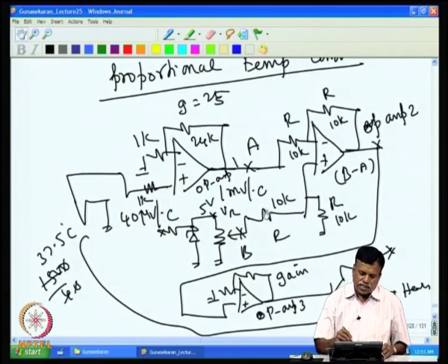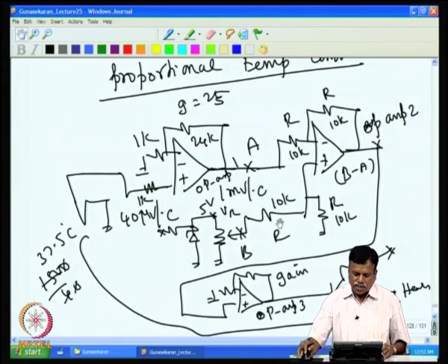So, this resistance must have at least 1% error or better to avoid the common mode voltage, because when we are varying this, then this voltage also latches up to the same value when the loop is balanced. So, when we are changing this preset at different temperature, then the common mode error will come in. So, here the op amp is not a serious issue, selection of the resistance is a matter of concern here.